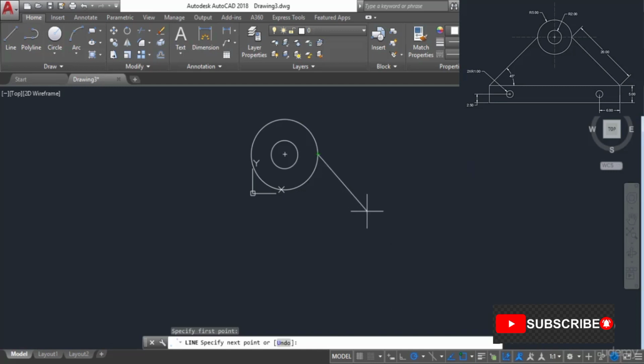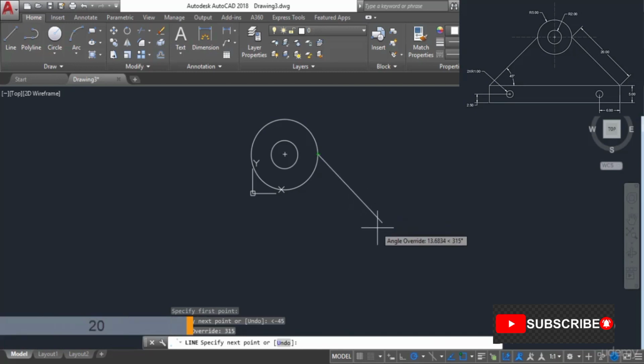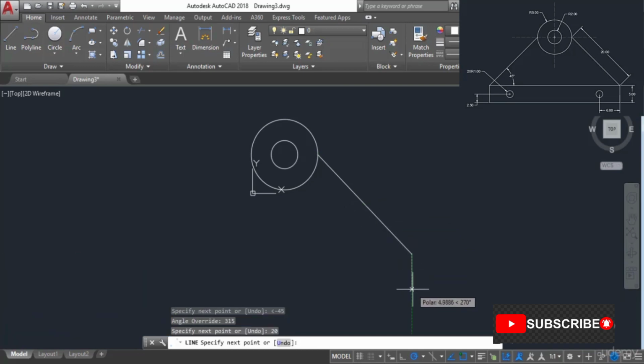Now we need to incline this line at an angle of 45 degrees. So let's type the angle sign, and since this line is inclining in the downward direction, we need to enter -45 and press enter. Okay, so there we have it. Now the length of this line is 20 units. So let's type 20 and press enter. Now move it in the downward direction and enter a length of 5 units and press enter. So there we have it.